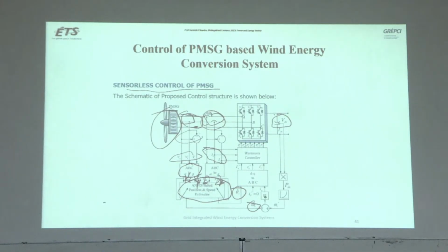So on the DC link, this is the grid side and this is the generator side control. Okay, so you are measuring VDC, IDC, which gives you power at the DC link. You use this for MPPT, which we have already discussed, which gives the reference speed. This is the estimated speed. Using a PI controller, it will give you the IQ reference. ID reference should be 0 as we had discussed before. And then DQ to ABC transformation. And here is the reference current for phases ABC, and these are the measured currents. So this is how you generate the signal using PWM.